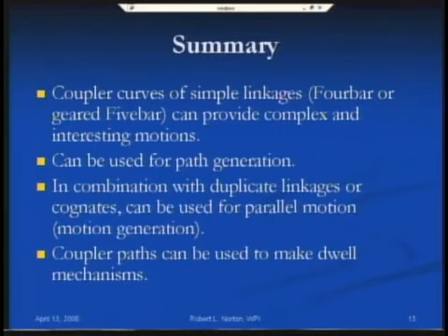And I can deal with that by introducing duplicate linkages or cognates of the same linkage, and then I can get what's called parallel motion, in which I control a line in the plane to follow the path of interest, which would be the coupler curve, and every point on that line follows the same path, thus the parallel motion terminology. And I can also use coupler paths to make dwell mechanisms, and that's the subject of another tape.